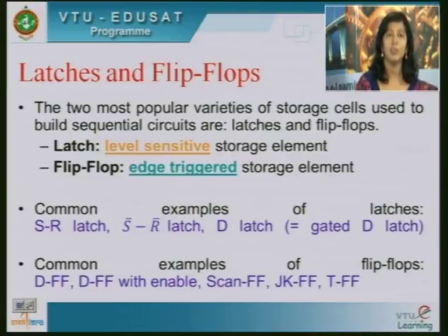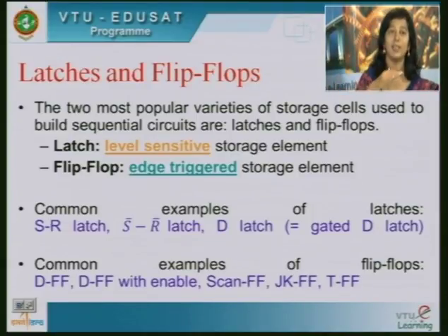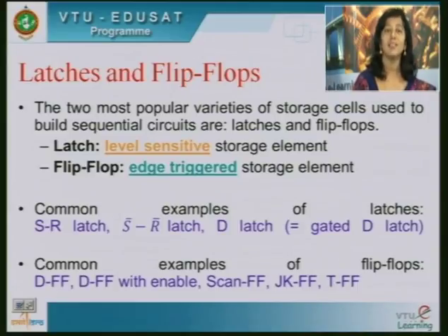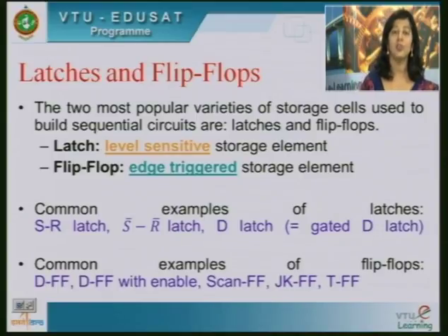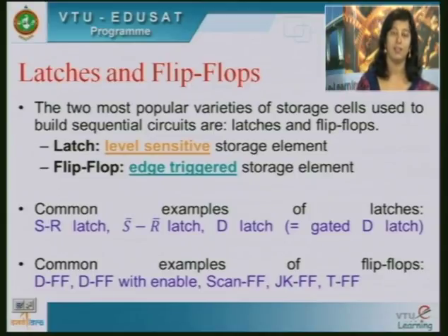So, what is the difference between both? A latch is nothing but a level sensitive storage element. That is, it senses a level, either a high or a low. So, it detects the levels and works according to levels, whereas the flip-flop is an edge triggered storage element. Usually the clock edges which I spoke of in the previous slide, positive or negative edge, that detects the edge, it's a flip-flop.